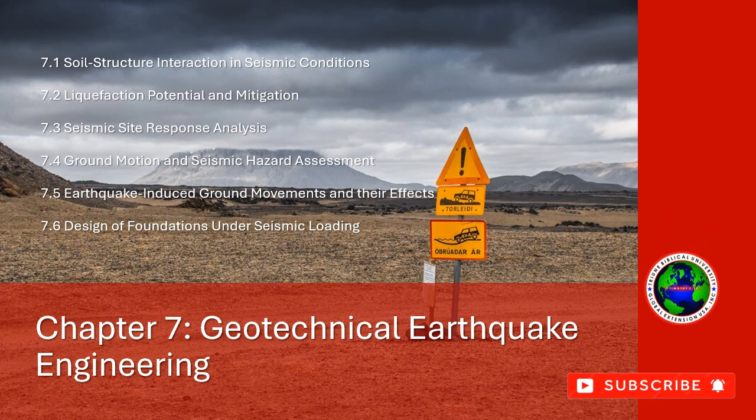4. Wave types. P waves, primary waves. These are the fastest seismic waves and are typically the first to arrive at a site. They cause compressional motion in the soil and are usually less damaging than other waves. S waves, secondary waves. These waves cause shear motion and are slower than P waves. S waves are typically more destructive as they produce ground displacement in two perpendicular directions.